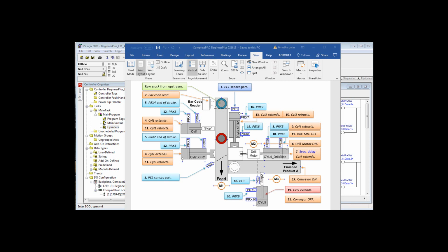And then when you get back to the retracted position, you may want to let the drill motor continue for a little while, spinning the bit to cool it off. Because remember, it acts like a centrifugal fan somewhat. So it cools off the bit a little bit to leave it run. These are just all little fine things that you can add into your program on a more practical basis.